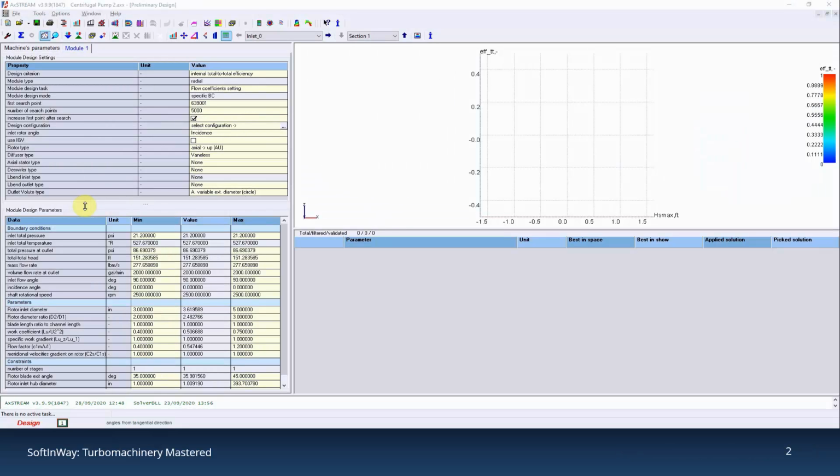Designing pumps which meet the wide range of industry applications and standards can be very challenging if you don't have the right tools to support your design process. As I'm sure you know, cavitation is to a pump what a wooden stake is to a vampire, and parameters like efficiency take second priority for the selection among designs able to reach the desired discharge conditions in the absence of cavitation. It is therefore critical to determine key parameters such as suction cavitation performance at the beginning of the design process so that development costs can be reduced and pump performance can be optimized.